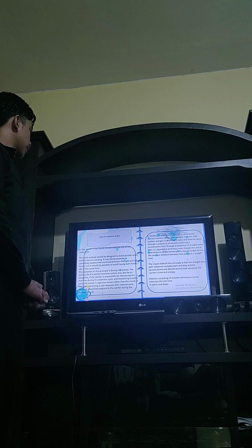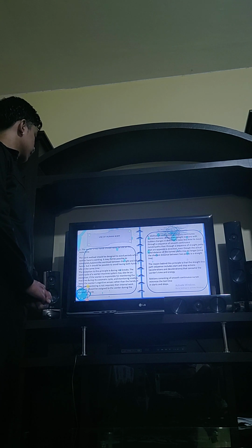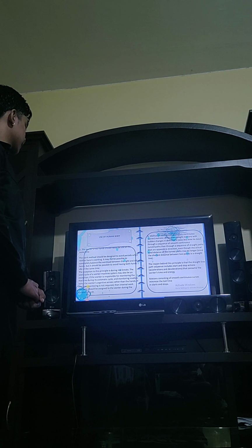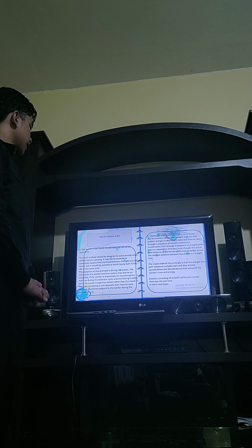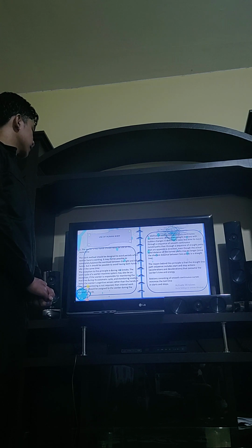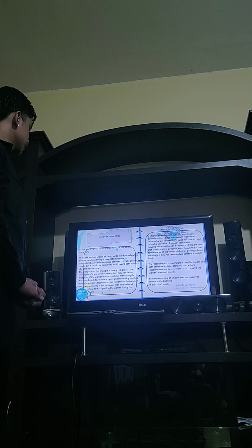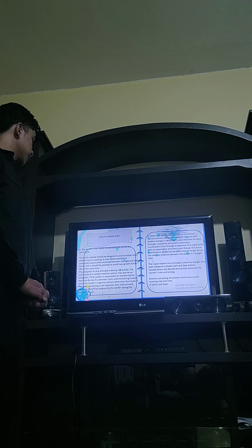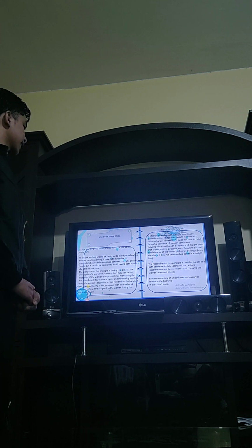The work cycle of a worker-machine system may also be an exception. If the worker is responsible for monitoring the machine during its automatic cycle, and monitoring involves using the worker's cognitive senses rather than the hands. If machine monitoring is not required, then internal work elements should be assigned to the worker during the automatic cycle.